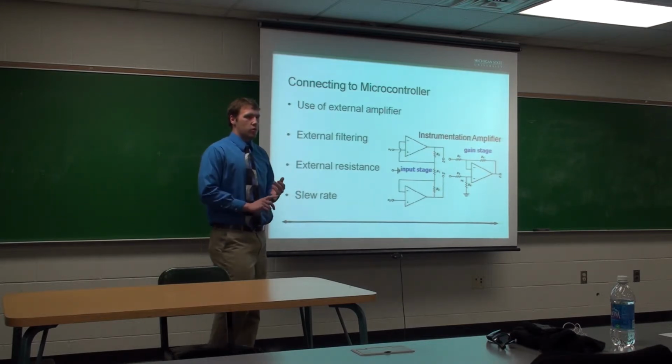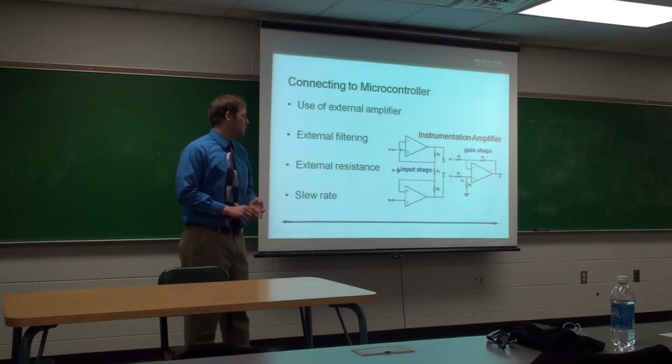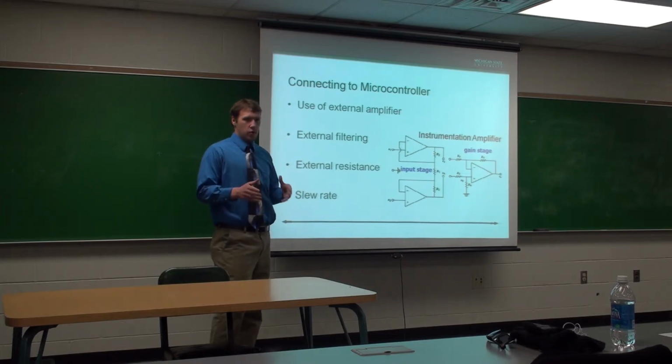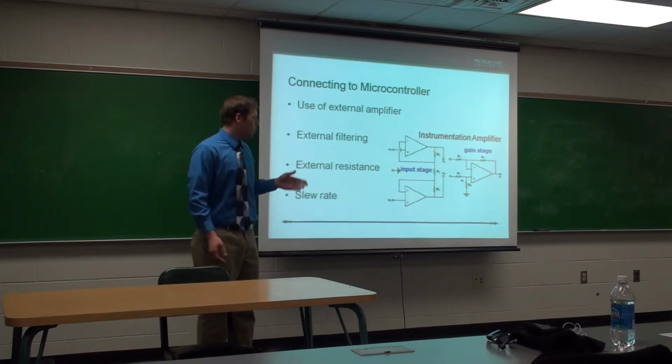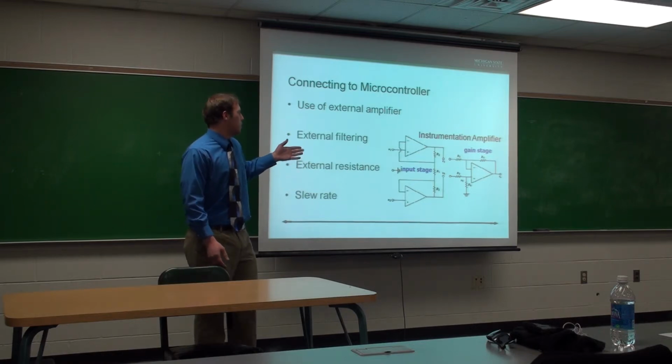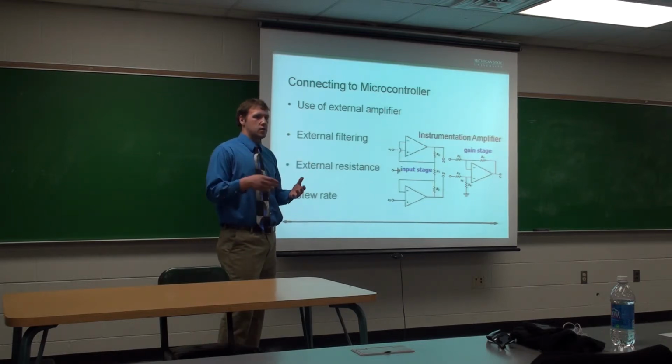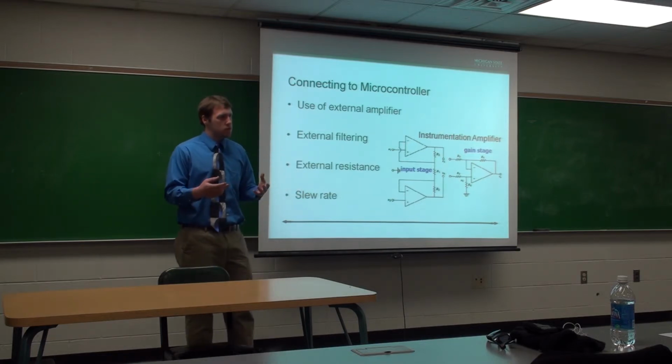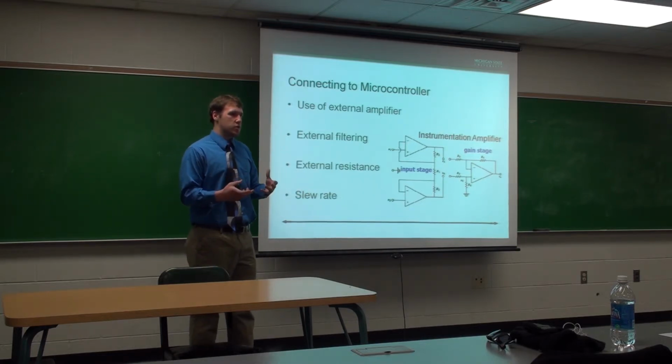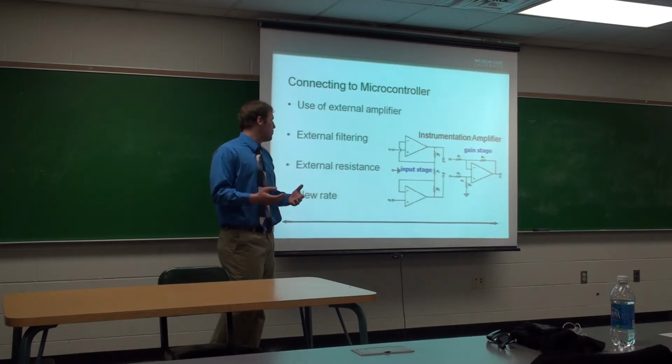It rejects all common mode noise. It has a high input impedance, and it also offers very low drift in your signal. We use this type of amplifier to step up these signals from the lab tests or patients, which tend to be in microvolts or millivolts. We want to get these into a range where we can actually view them and do something with them.